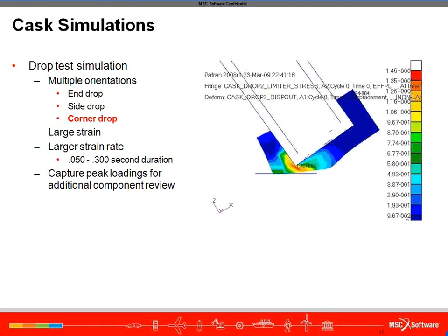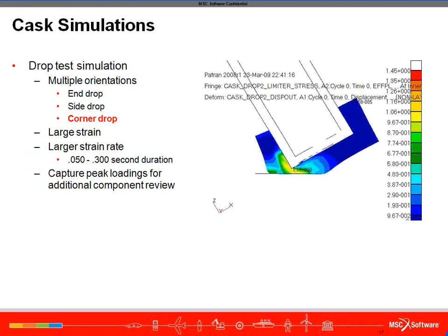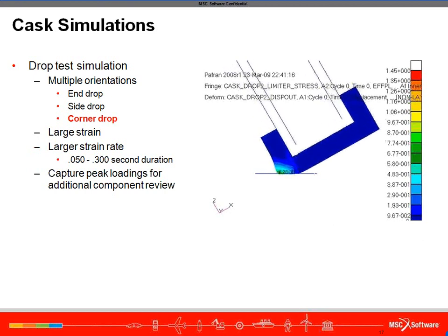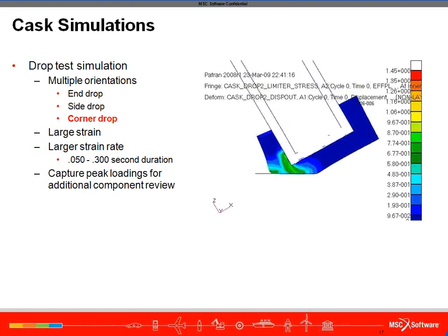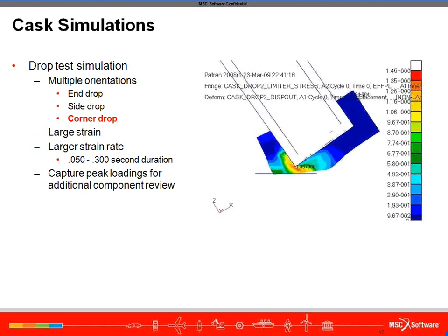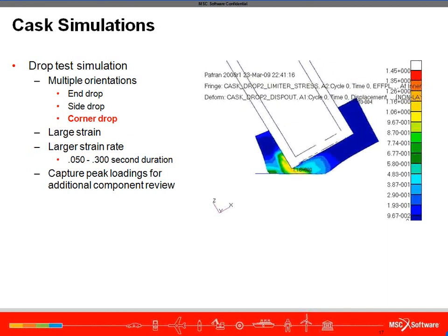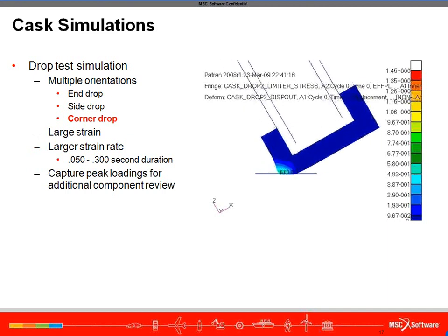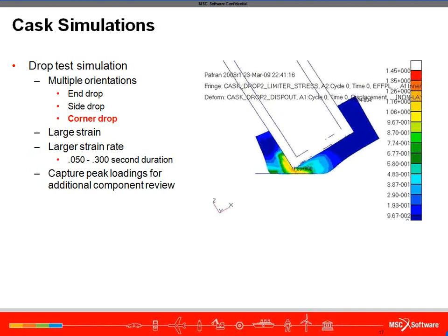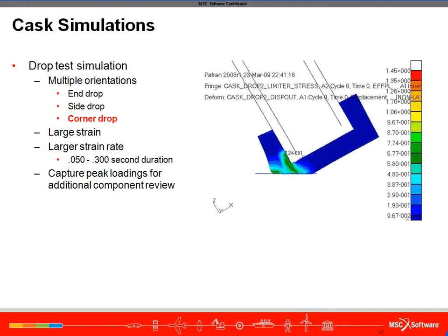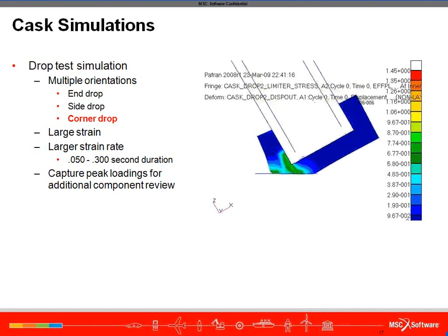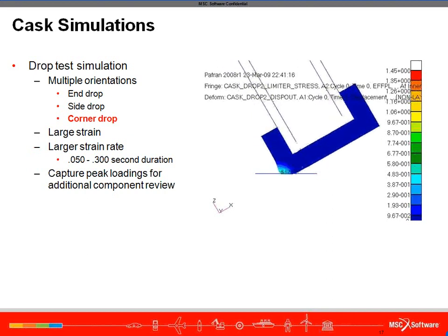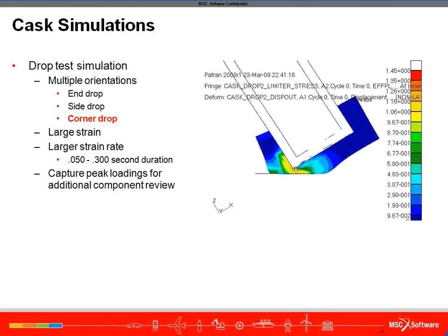In this case, what you're seeing is the plastic strain in the steel plate. Anywhere you see a color other than a dark blue, the material is experiencing stresses in excess of its yield point. So what that indicates is you're going to have some permanent deformations wherever you see a non-dark blue color. Based on the level of deformation that the limiter is experiencing, this may or may not be surprising to the designer, but there's certainly value to seeing the distribution of these strains that might allow minor or major adjustments to a design.